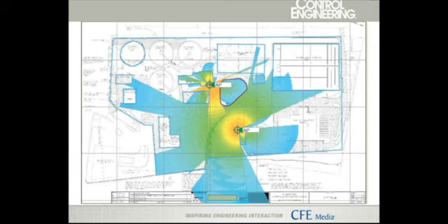The other AP is at the relative upper left, where the orange is the control building. The propagation strength varies from red and orange being the strongest to blue being the lowest. You can see that a substantial amount of the plant is covered using just 2 APs.